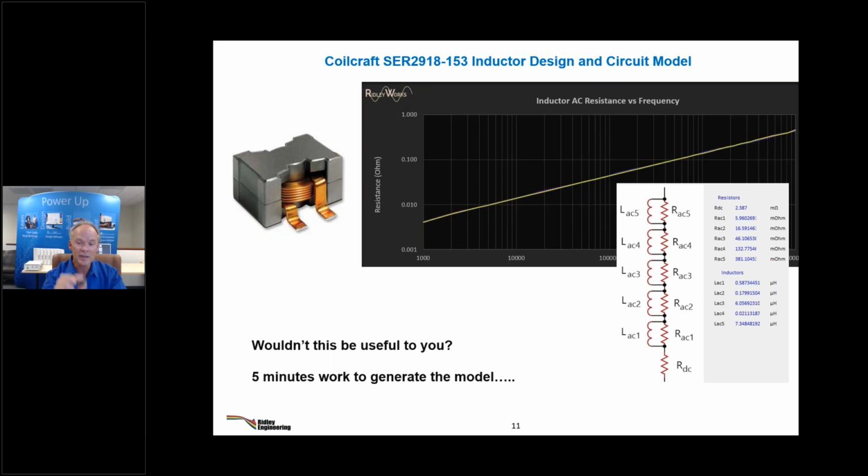When you're in a buck inductor, does it matter? No, it doesn't matter because the AC is too small. If you gapped your core like that and you put the windings right next to it like that, this thing would probably fry. So just move the gap away. Again, my philosophy is don't analyze a bad situation, make a good situation, and then you don't need to do the analysis because you've eliminated the gap loss. Hopefully that answered the question there.